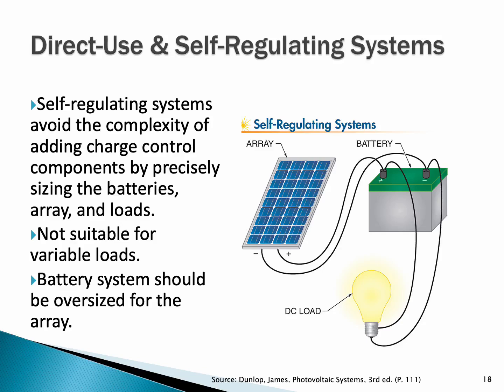So nothing new there, but what happens is, like on navigation buoys in the water, you'll have a light strobing and/or a constant light, and the battery is sized for the duration of that light being on during the evening, and then the array is sized to meet the battery's needs to fill up that battery during the day.